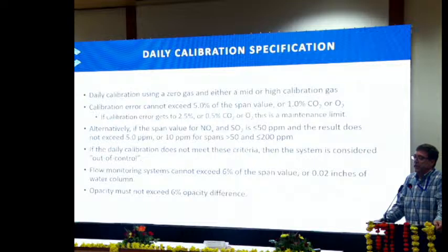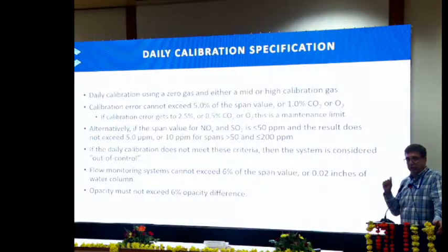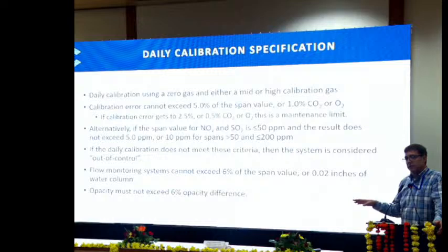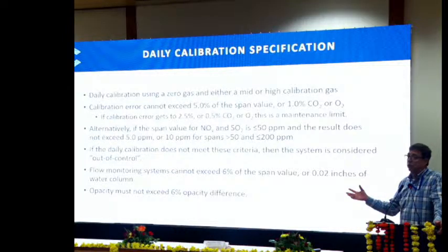So if we have this set up with a special flag, when we reach that point, operations or your technicians, whoever is maintaining your system, can go and address the system before you exceed the calibration error limit, and keep the system operating normally without having invalid data. Just because you reach 2.5% doesn't mean you're invalidating data. It just means you're going to go into a QA process of cleaning and maintenance and address the issue.